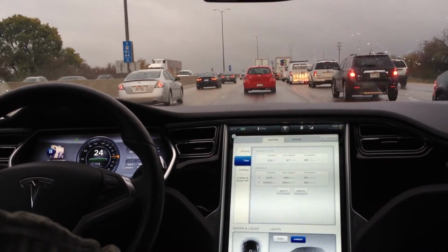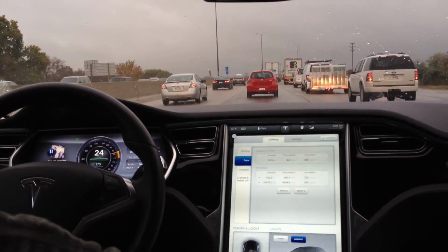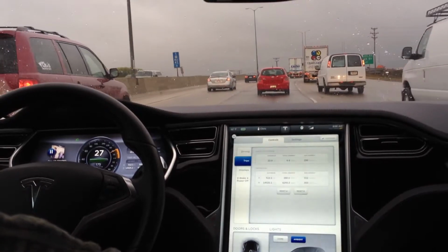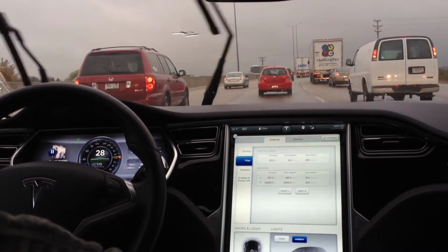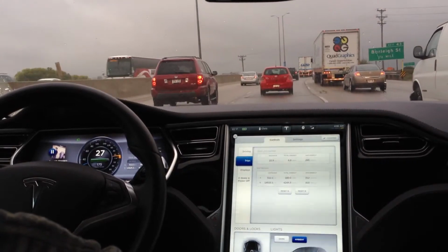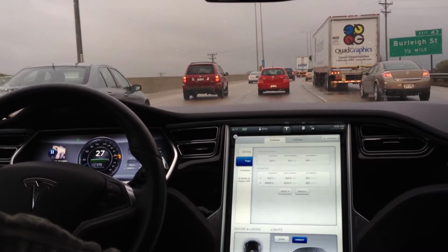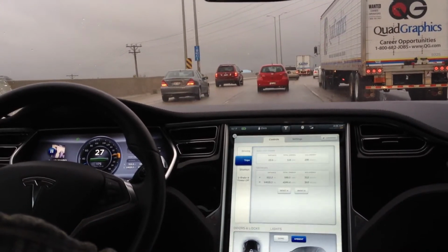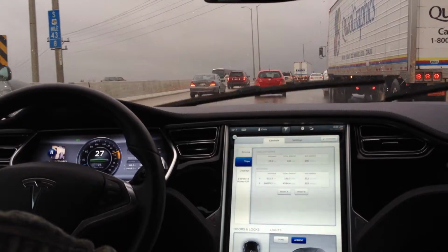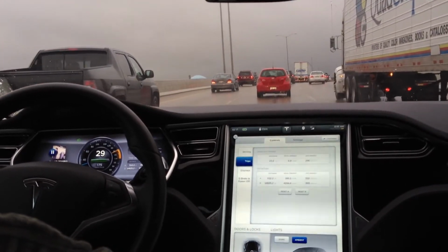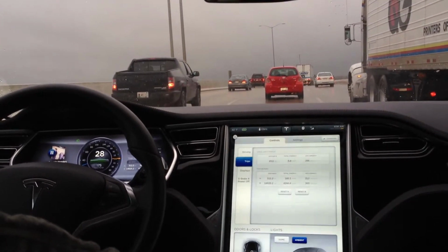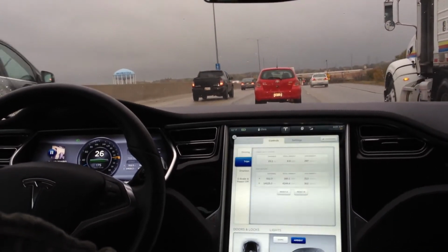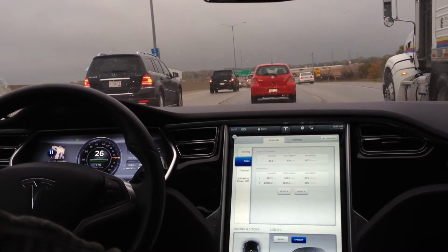Now, for those that aren't quite as familiar with electric vehicles, consumed means power I'm taking out of the battery pack and using for motion, so driving the car. Green, or regeneration, is power that I'm taking from the motion of the car using the electric motor of the vehicle, a three-phase induction motor, to generate that electricity and put it back into the battery, using the motor and the drag from that generation to slow the vehicle down.